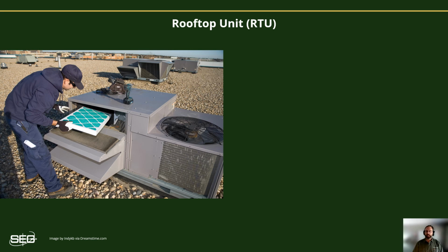I've been talking about air handlers, but a special note about RTUs, which stands for rooftop units. These units are oftentimes the HVAC little workhorses for your small to medium-sized buildings, usually providing both heating, cooling, as well as ventilation. RTUs may or may not have an outside air economizer damper on them. This would be frequently a matter of their age and size, although nowadays most building energy codes do require that RTUs be installed with economizers. But this was not always the case for those older units.